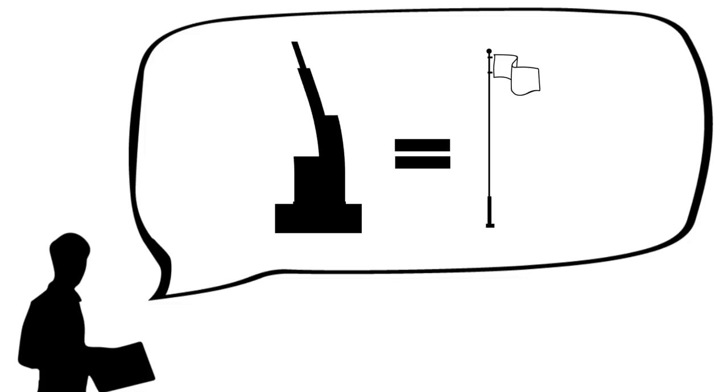So the buckling for a tall building, first of all, buildings aren't quite that tall and slender like a flagpole. And secondly, there would be other factors for the building that would require beefier structure, and it would be unlikely that buckling would control. But yes, same principle.